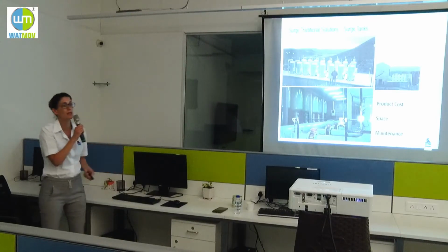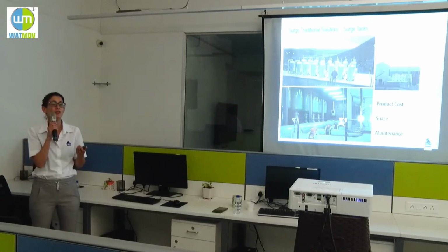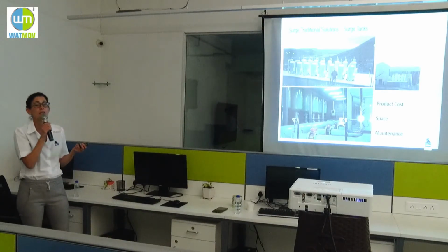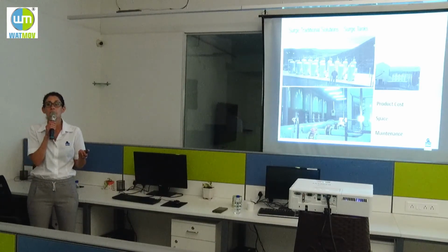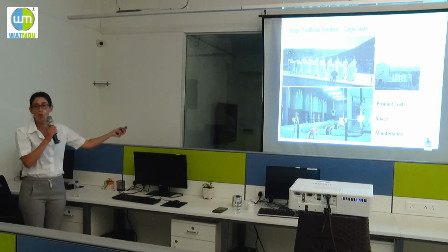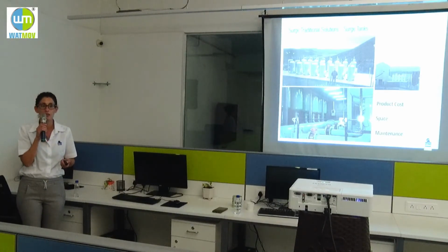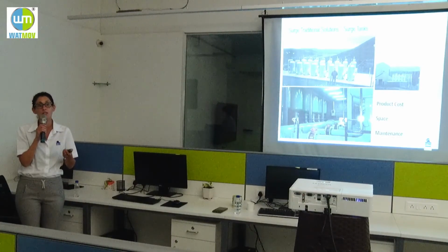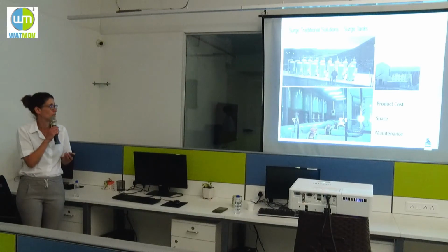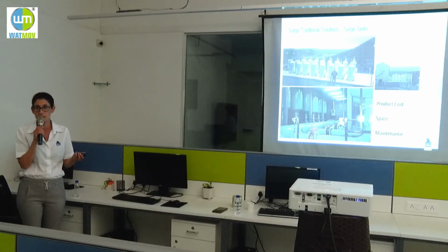You can see here a surge tank, I think from Argentina, for a project. So think about it, when you have a lot of surge tanks, you need a lot of space, you need infrastructure. If there is an issue with the weather, too hot, too cold, you need to give it a special room to take into account the temperatures. And the product cost is much more expensive, 6 to 8 times more expensive than surge anticipating valves and air valves. And the space is not always available, and there's the issue of maintenance, okay?